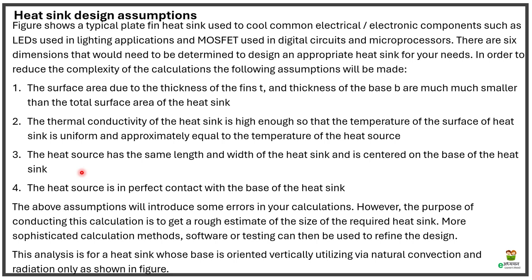So we are putting this heat source in the center of the heat sinks. Then the fourth assumption will be that the heat source is in perfect contact with the base of the heat sink. So here we are considering that the surfaces of the heat source and the base will be perfectly aligned and there will not be any deviation or a gap in between. So it will match completely, in 100% contact with the heat sinks.